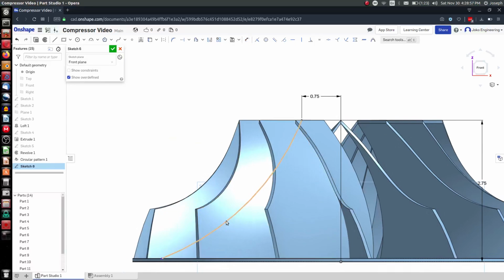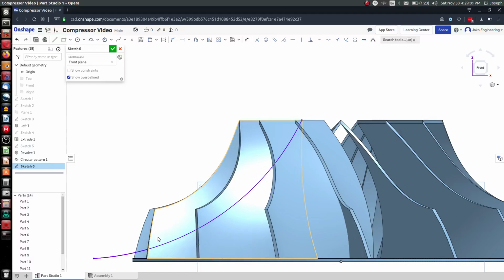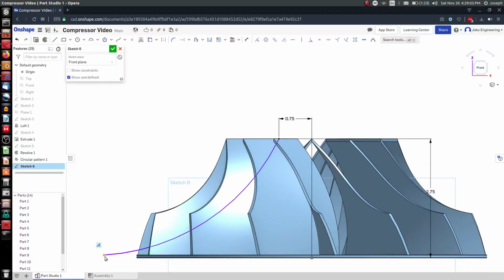Finally, it's looking for a particular radius, and I guess I should be dimensioning this bottom part of this arc a little bit better too. We'll grab the end of this arc to the edge. I'll make that something like 0.25.